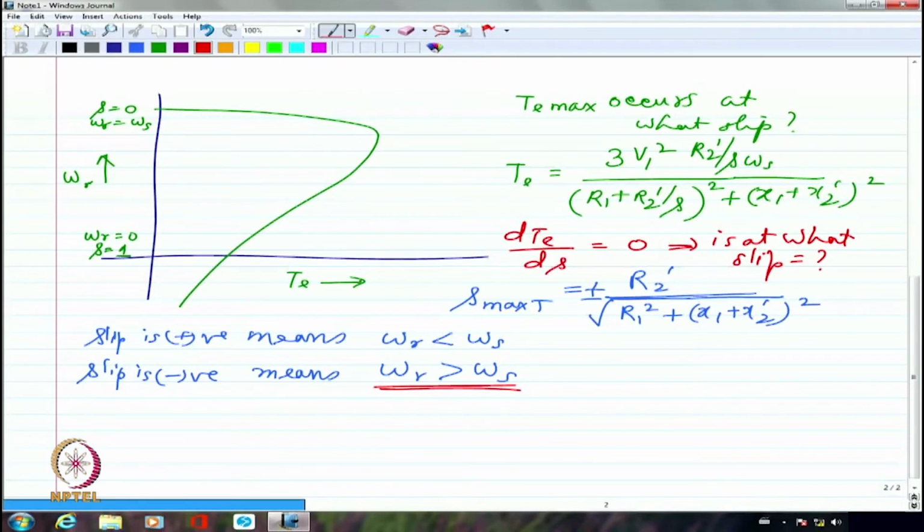So the gravity can make the speed go up beyond whatever is the synchronous speed also. In which case, it can go into slip being negative. That's what I mean by having a prime mover. The prime mover can be a turbine, a wind turbine or IC engine or whatever, it doesn't matter, but it can also be gravitational pull.